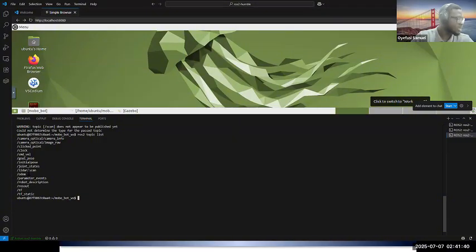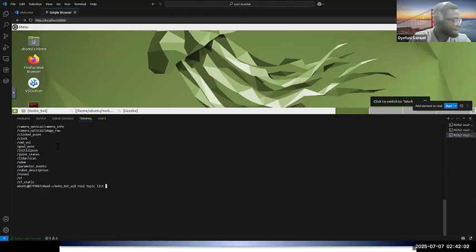There's a scan topic where we remapped it. Like I said, you can also remap your topics. There are different ways of doing that. You do that when you're writing the LiDAR scan code, in the robot description for the LiDAR sensor. You remap the scan topic. What we're going to do is echo the LiDAR /scan. So we're going to do ros2 topic echo /lidar/scan. When I try it, you'll see it's going to give us some messages.